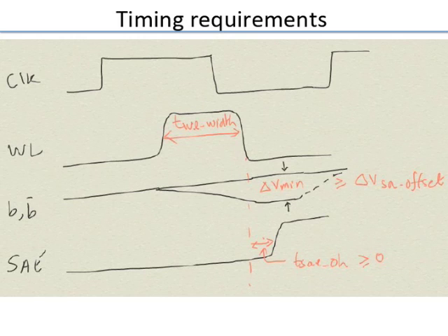How much time does it take for my memory to generate my minimum voltage which can be detected by the sensor? So that is the timing generation I need to do. You can do simulations and see how much it takes, and somehow in the chip you try to put in that delay generator which will generate that.